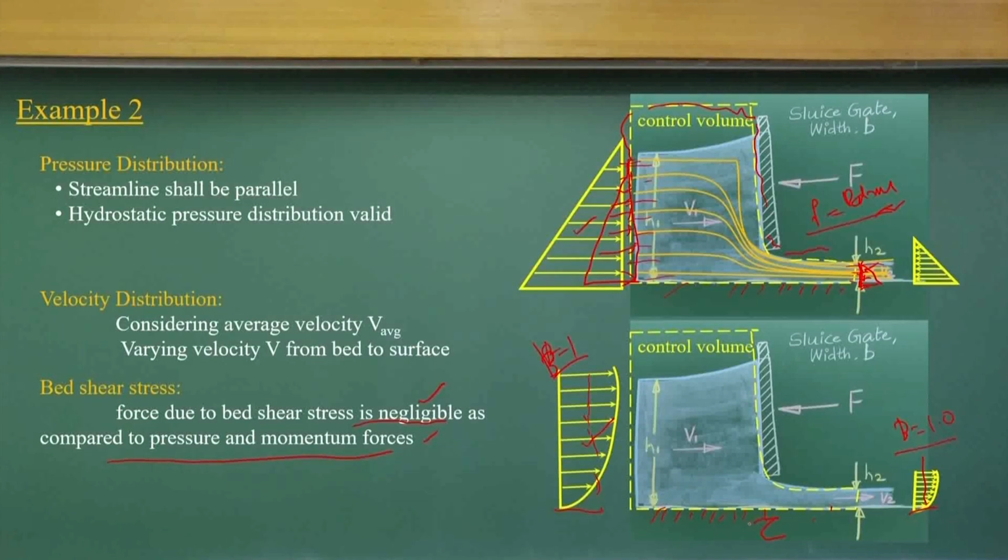Please remember, there is a shear force acting on the bed, but in these problems, the force due to the hydrostatic pressure distribution and the change of momentum flux are much higher order compared to the shear stress at the bottom.